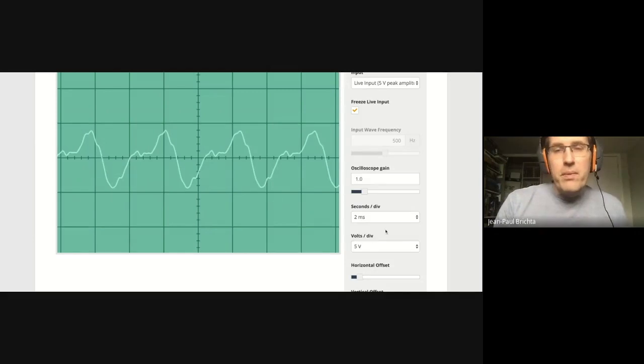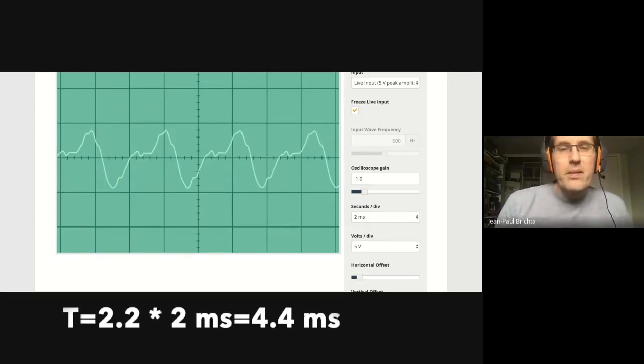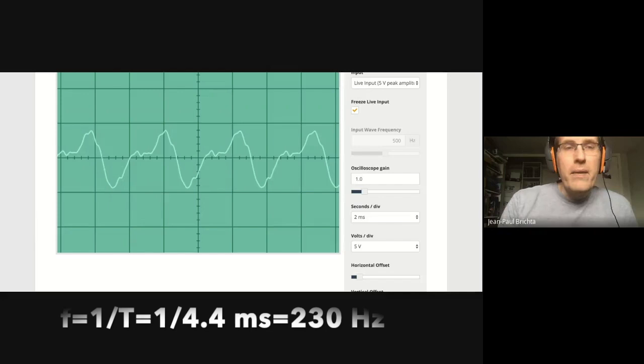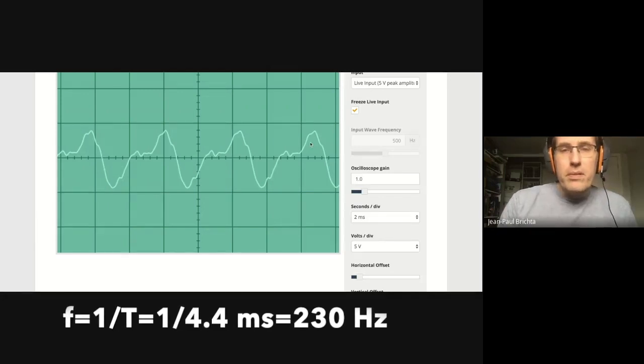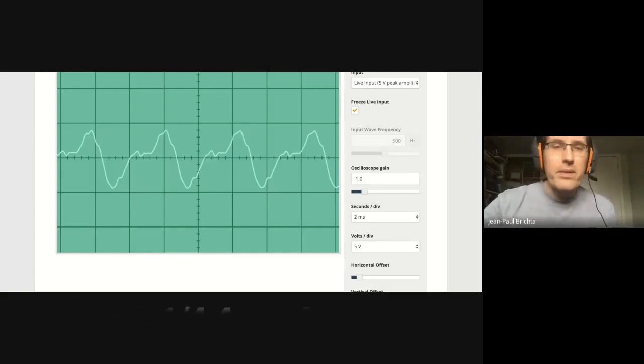And then if I multiply that by the seconds per division, 2.2 times 2 milliseconds is 4.4 milliseconds for one period. And then I can go back and calculate that frequency, and it's about 230 hertz, which is still quite low. But like I said, I have a relatively low humming voice.